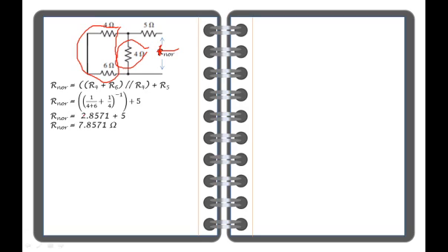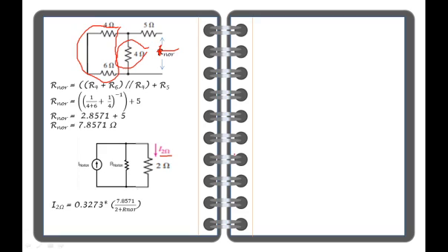After getting the Norton's equivalent resistance, we're going to combine the two, the Norton's current and the Norton's resistance, wherein the Norton's current is the short circuit current that we solved previously. Now we're going to get the current at the 2 ohm resistor. To get it, we may use mesh analysis or nodal analysis, but on this part, I'm using the so-called current division theorem.